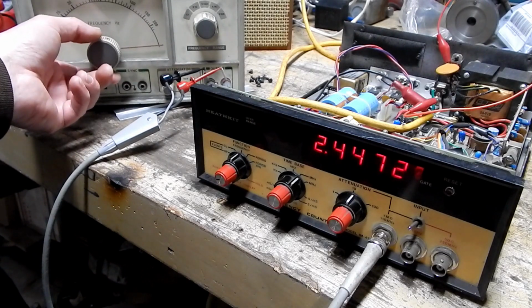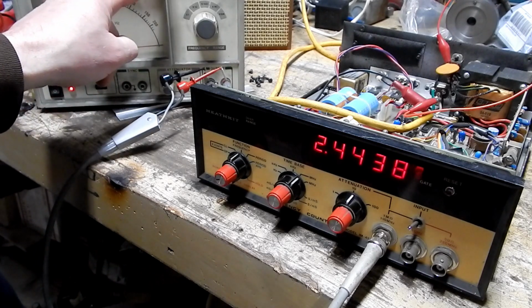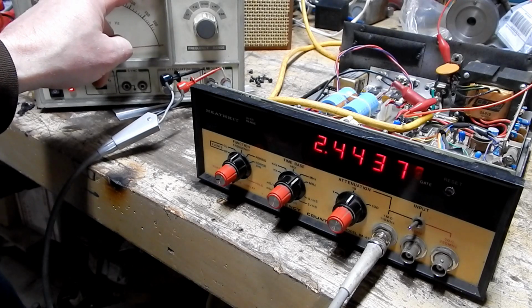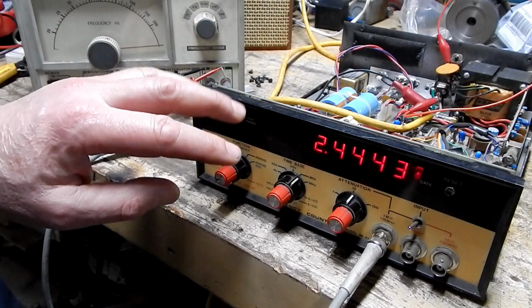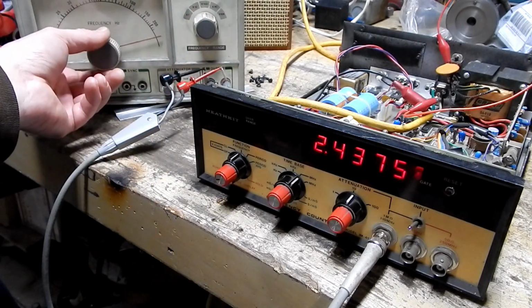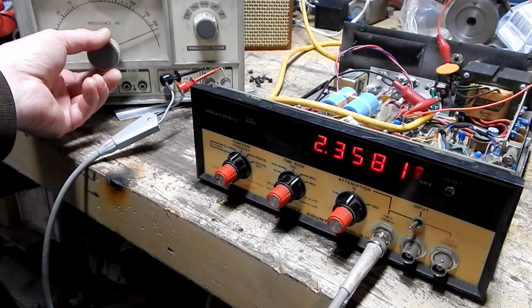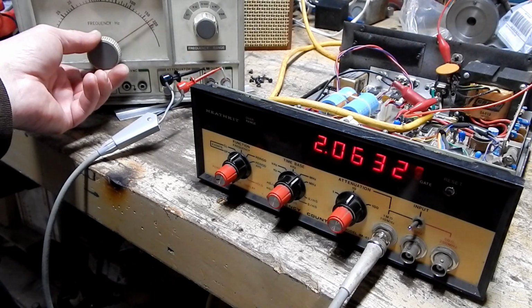This generator is actually able to output about 2.4 megahertz, but they're saying on the generator that it's 20 hertz to 2 megahertz. Probably what happens after 2 megahertz is that it's not very stable, or the output drops off. So they're basically saying, hey, it doesn't just shut off at 2 megahertz, but 2 megahertz is where the cookie starts to crumble.